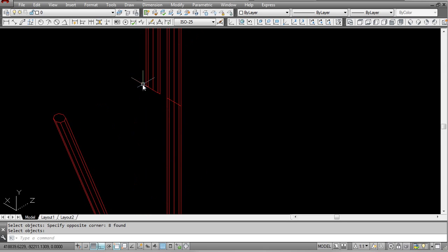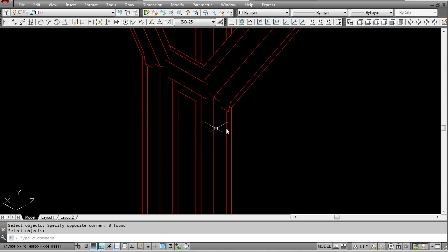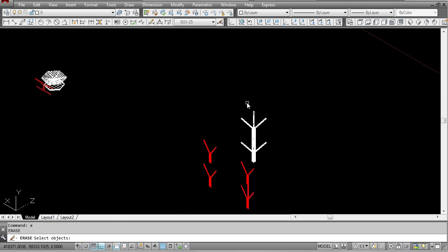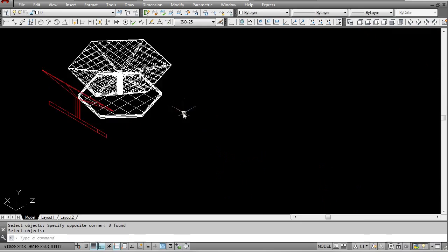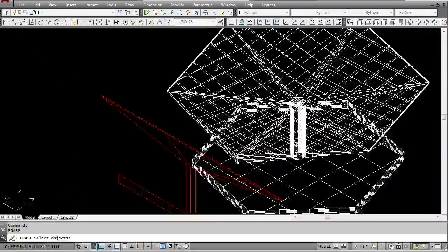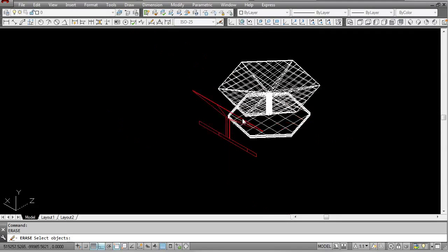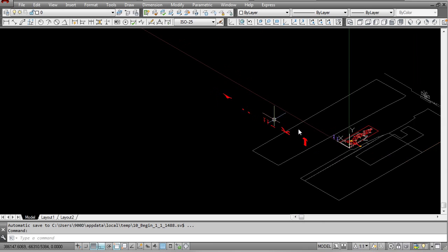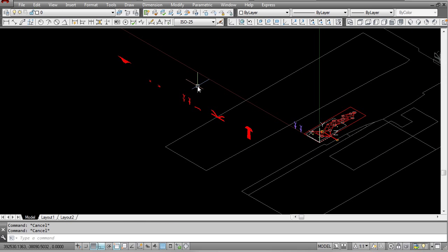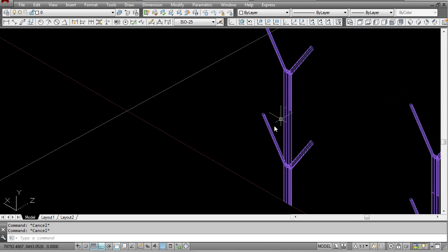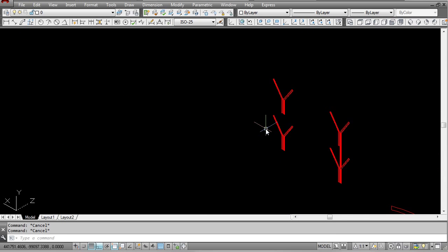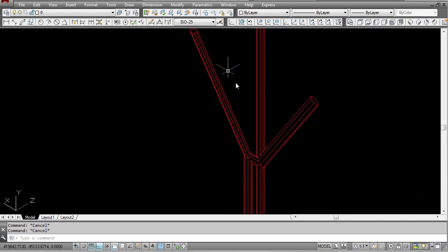So again, with these, you will see that it is a lot better. You'll see that this hidden line is working quite well. We're not necessarily getting these lines because we don't have any edges in those placements, but you will see that you're getting the right geometry, and it's all looking like a good hidden line render. These 3D objects have completely collapsed into just a couple of edges. So all of that now gets deleted, and I'm going to have to explode this and move everything back into place. And you can also just compare the difference between the flatten command giving us this result and the flatshot command giving us this result.